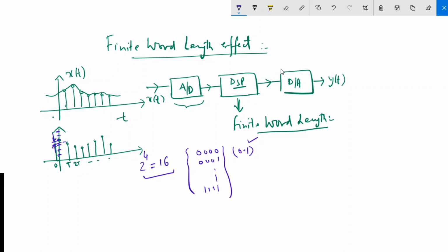It means it will go maybe to 0, that is 0, 0, 0. And this is what is done in the final stage, that is your binary coding. So after binary coding, for each sample, you get a binary number. If this is suppose any sample value out of these 16 sets, so you may have this value as 0, 1, 0, 0 suppose. So you generate a 4-bit code for each sample. For this sample, you again have a 4-bit code, maybe 1, 0, 1, 0, anything, and so on.